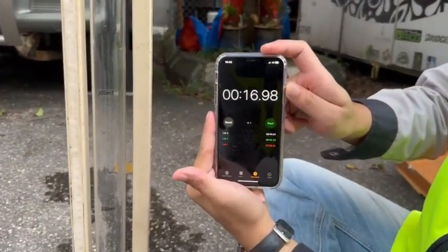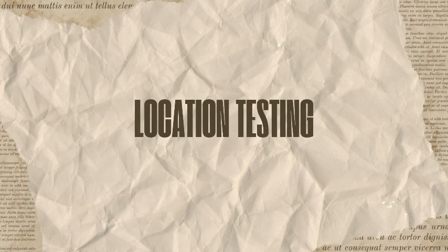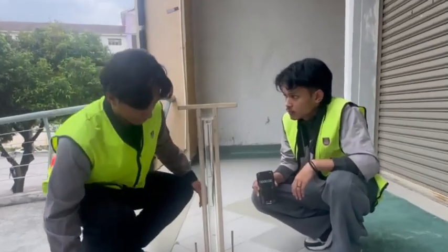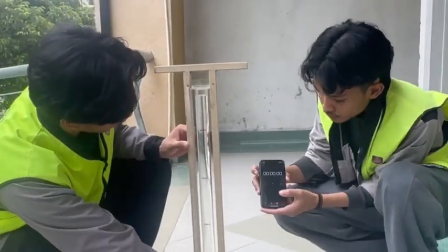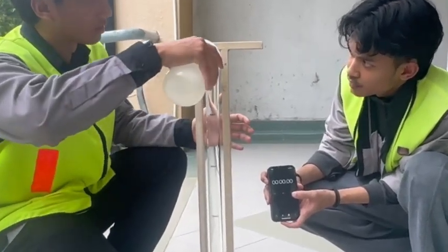For this test, there are two turning points we collect. For the first reading, we take the 400mm mark, and the second one is the 100mm mark. Also, repeat the procedure that we have done on a different pavement surface, which is a fine surface.